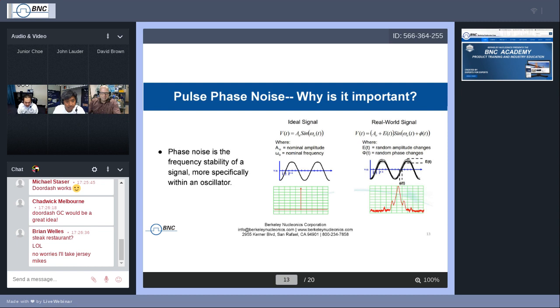Now, imagine any type of communication signal, a data link, even your cell phone. If you have a noisy background, or the person on the other side's voice is getting choppy and hard to understand, that's basically phase noise. That's why it is quite critical for any microwave RF system designer to understand where their phase noise is coming from, to build a strategy to mitigate this noise.